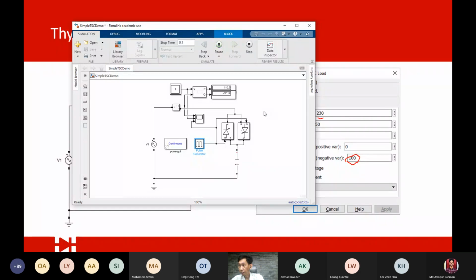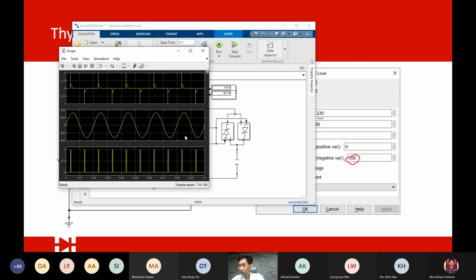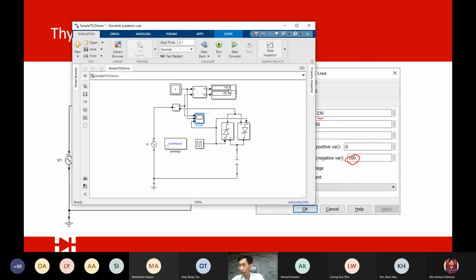See, now the difference is that reactive power is reduced from 100 to 62, and now I got active power going in already. That is what happened to the current waveform. We cut it a different way, so you will see that we control this power.